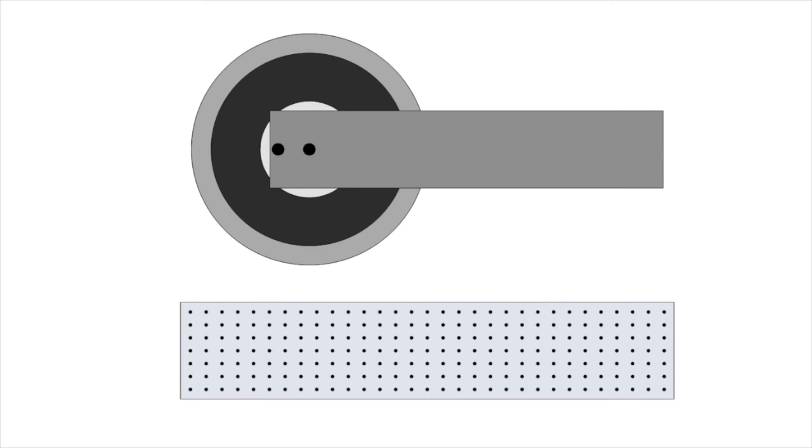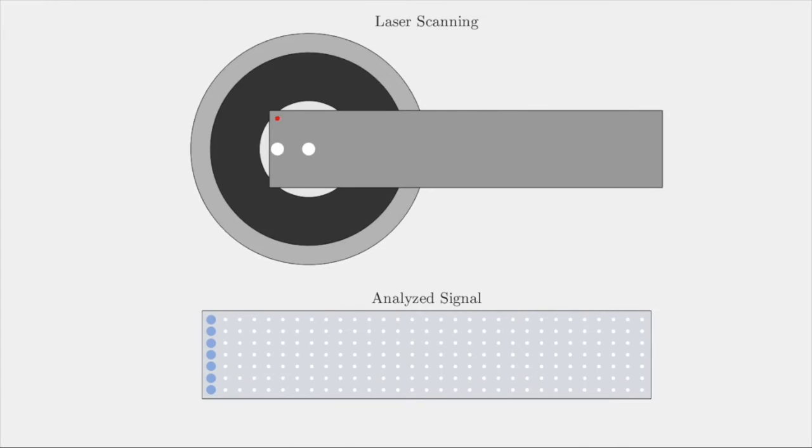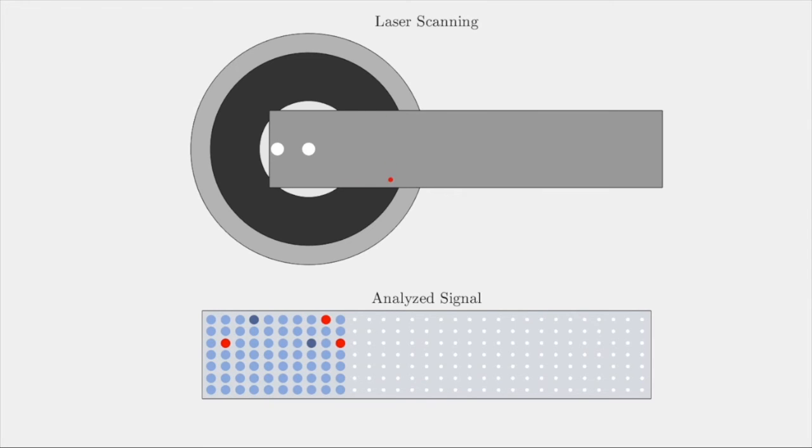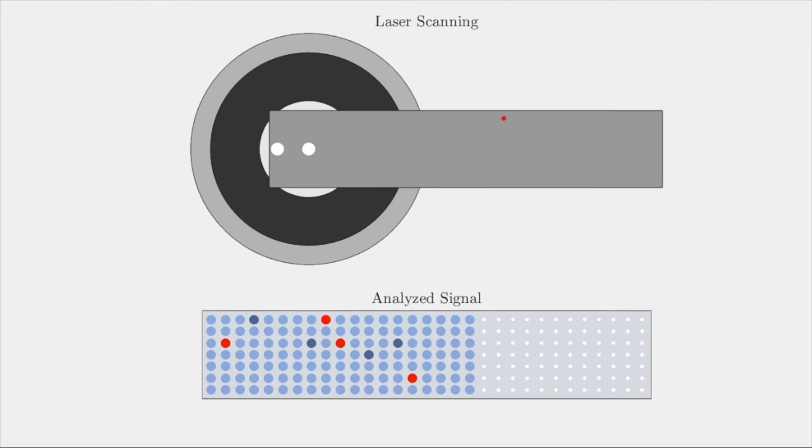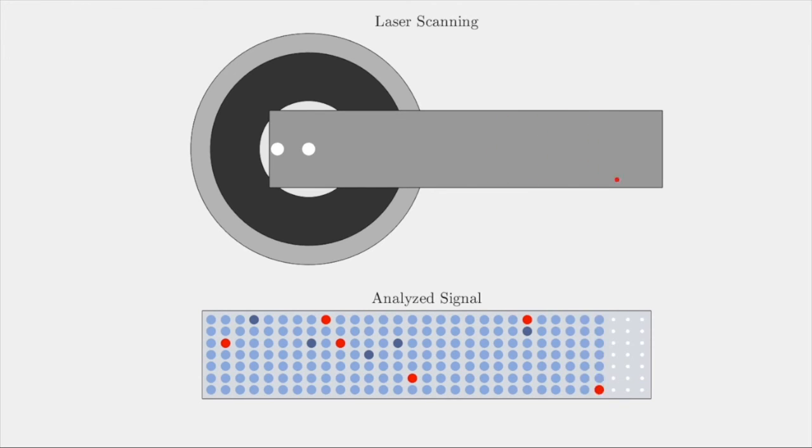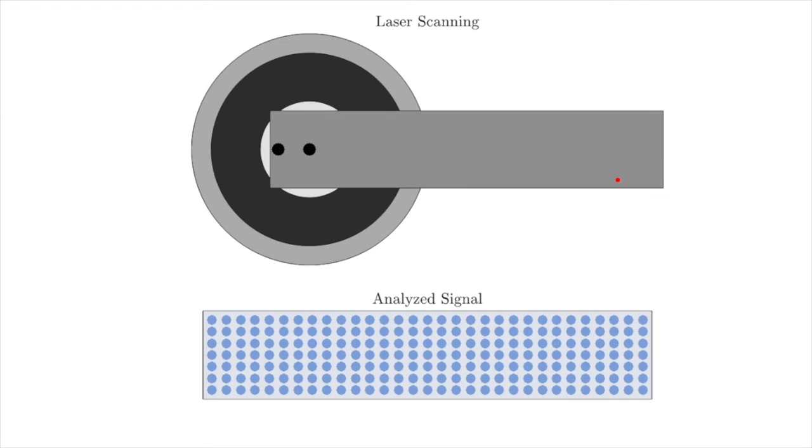The measurement procedure starts with identifying the points of interest, which are presented as white or black dots. Once prompted, the scanner head starts to measure the velocity at these points and categorize them in mainly three categories: optimal, which is the light blue, valid, which is the dark blue, and invalid, which is the red. Once it is done from the first scan, the scanner repeats the measurement at the non-optimal points to achieve optimality.